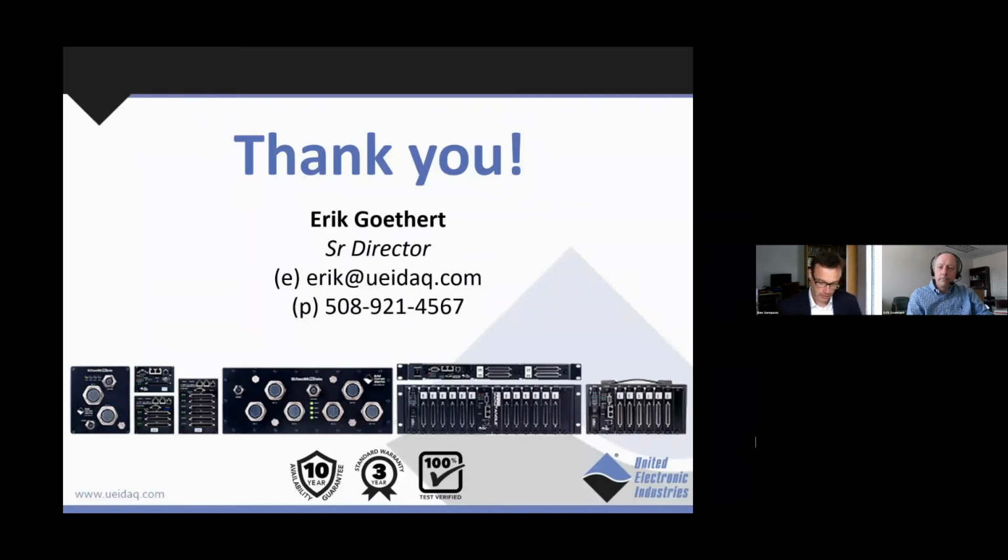And what about analog inputs? Can you take those and put them on a 429 bus, for instance? Absolutely, we have a wide variety of analog input boards, and you select the one for your application. And the application running can read from the analog input and put it on the 1553 or 429 bus.